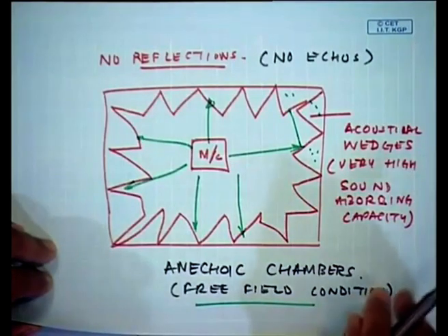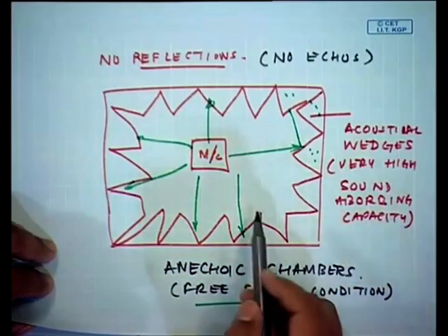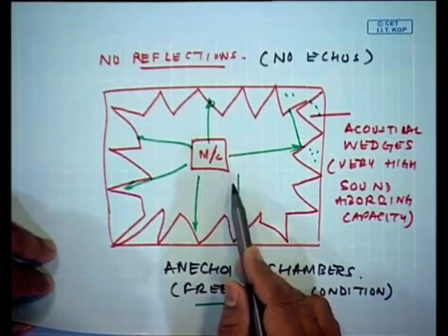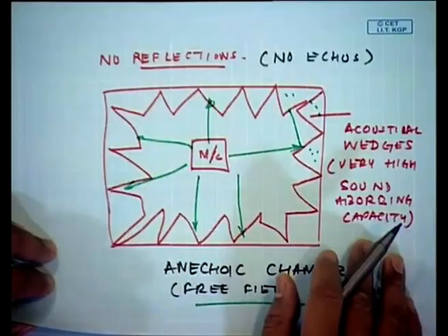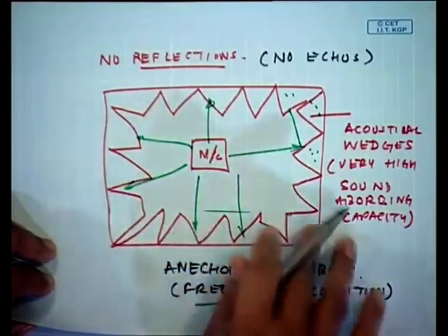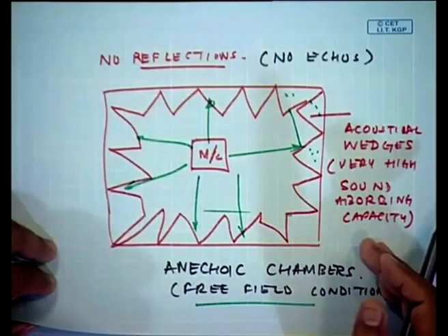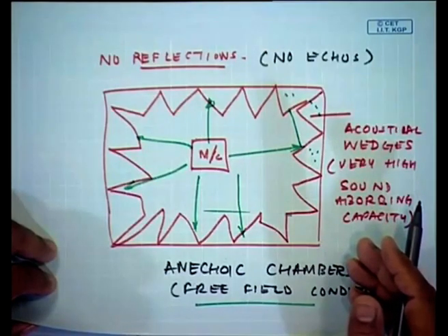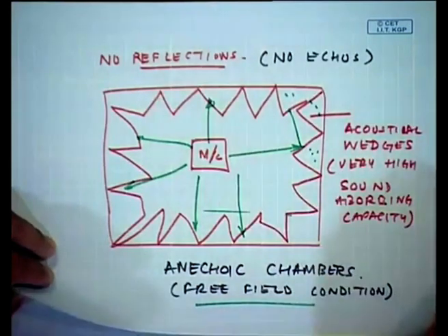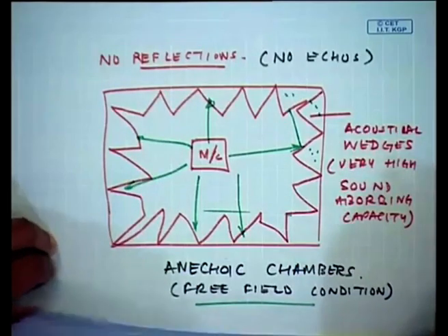Okay. So, when we do the noise leveling of a product or want to find out the sound radiated by the machine, we usually test them in such anechoic chambers. In fact, people test vehicles in such chambers. They can put a grating here and then drive in a vehicle, rev it up and measure the sound pressure level radiated by it. The same phenomenon is used in the electromagnetic absorption of radars, and such chambers are also there in the radar and communication centers, where they test antennas as well.